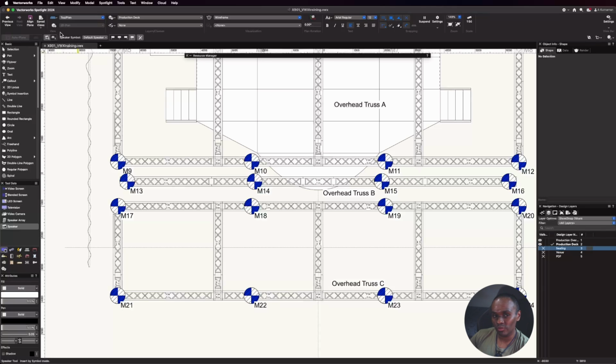Which means that if you bring in a catalog object, you can create your own custom size speakers. Whereas with symbols, we go by manufacturer and model. The ability to customize the size, dispersion and shape of the speakers is something which you don't get with your symbols. It's only available on your catalog.